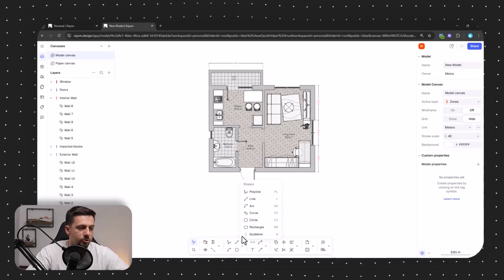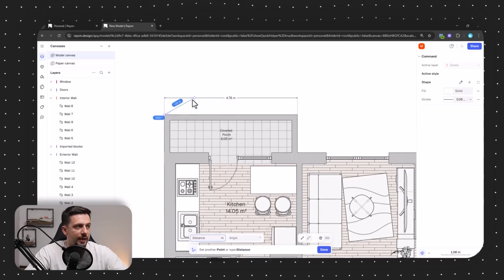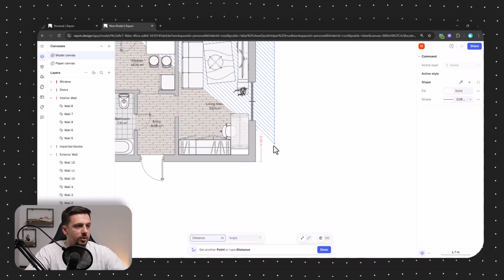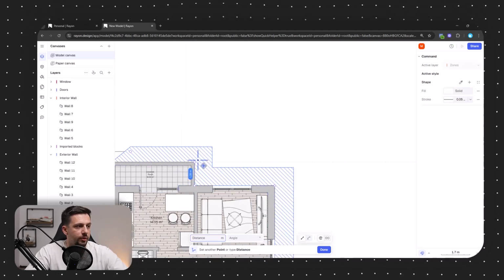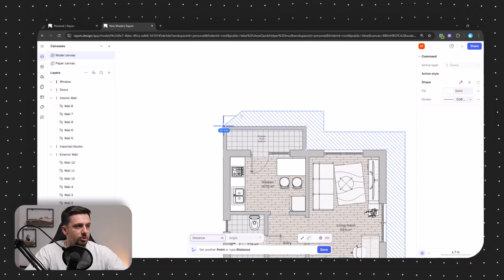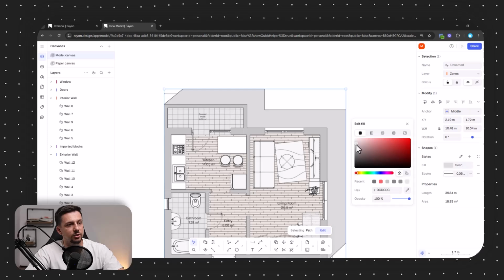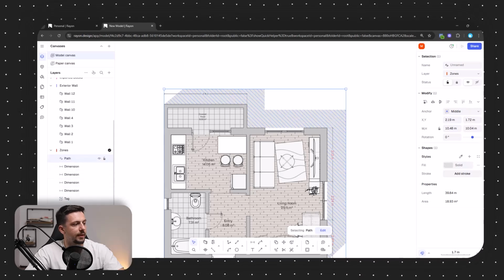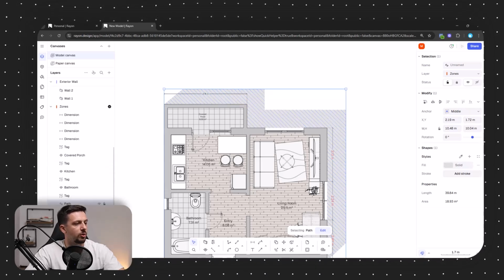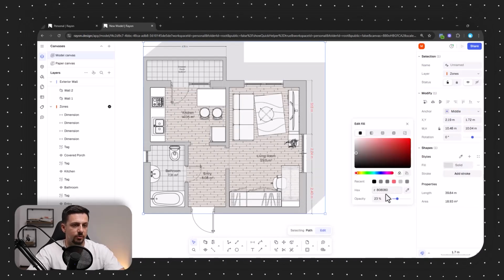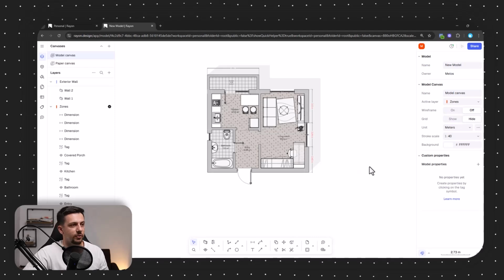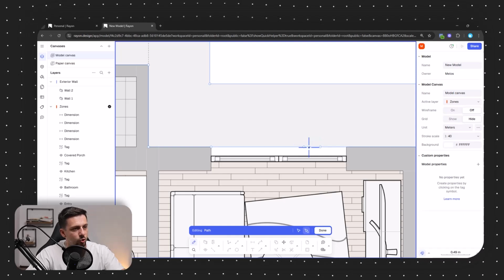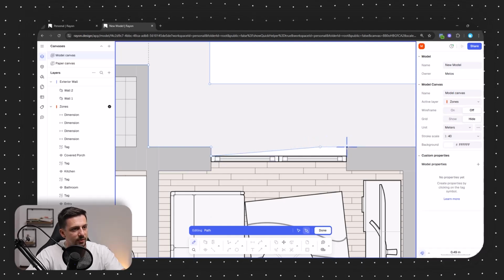If you want to stylize this even further, we can also add, for example, a shadow. So in order to add a shadow, we can just go at some sort of angle and draw something just like this. We can go downwards. Let's close this off over here on this corner, on this corner, on this corner, and then let's just click done. Okay, perfect. And then in solid, let's just choose something like this. Let's lower the opacity. The stroke, we can just take this off. And in terms of this path, we can just put it all the way in the back. That way it really does look like a shadow. So we can just leave it at something like this for now, for some extra style points. And maybe just to be even a bit more detailed, we can add 2 more points on this path, and then we can add them right on this corner.